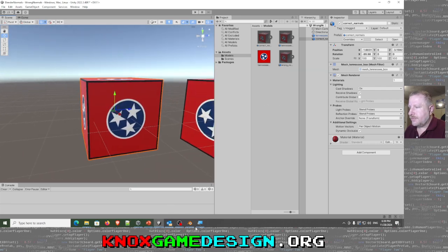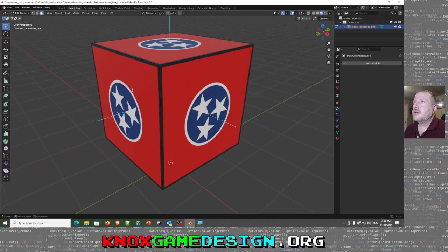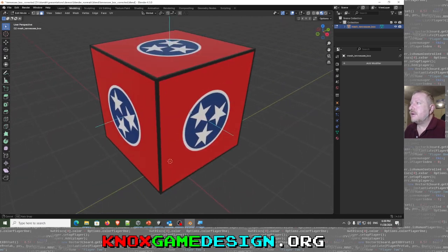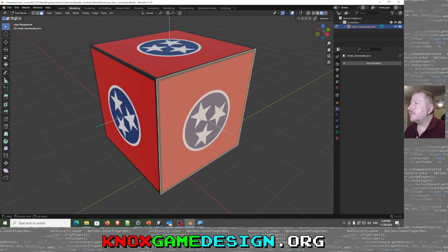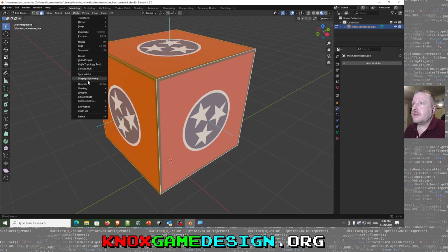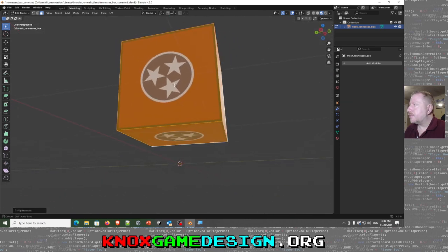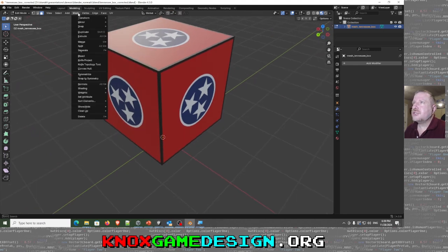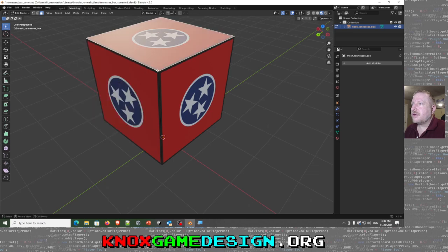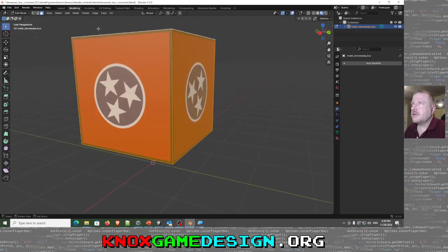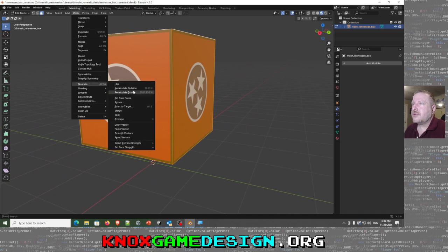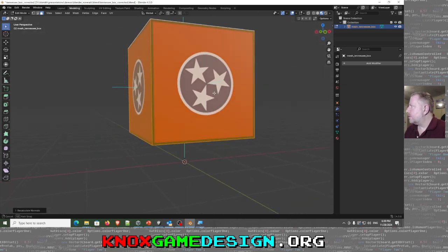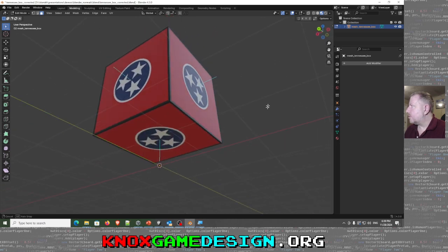The other option, as I mentioned, you can go back into Blender here and say we got a few of them that need to be flipped. Like actually, I'd select them all, mesh, and then normals, flip. So you won't be able to see anything in here because all the normals are flipped. But to fix that, you can go to mesh, normals, recalculate outside. Oh, you have to have it selected. Mesh, normals, recalculate outside. Yeah, so that fixes the normals as well. So they're all pointing outside.